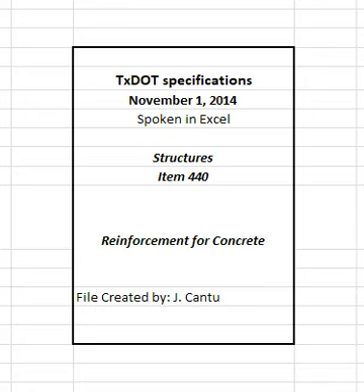Do not vary bars from plan placement by more than 1/4 in the plane of the bar perpendicular to the nearest surface of concrete. Provide a minimum 1 inch clear cover of concrete to the nearest surface of bar unless otherwise shown on the plans. For bridge slabs, the clear cover tolerance for the top mat of reinforcement is 0, plus 1/2 inch.